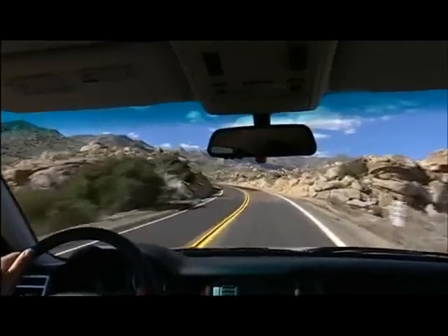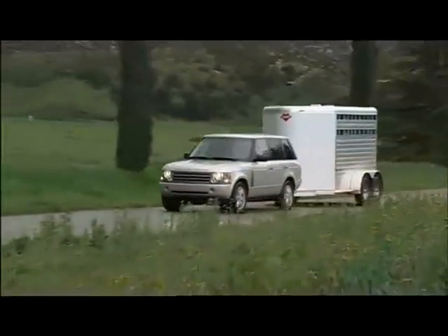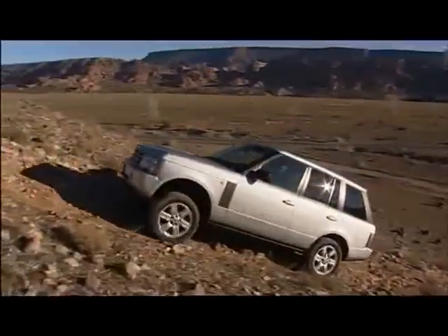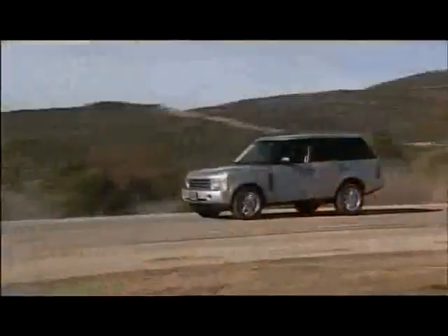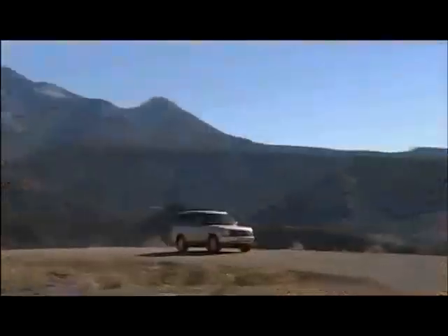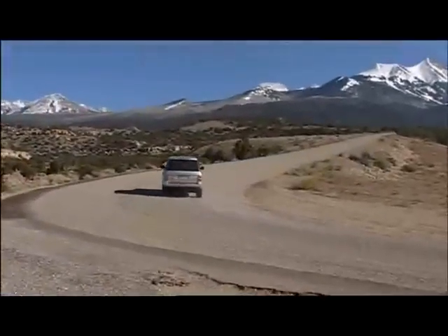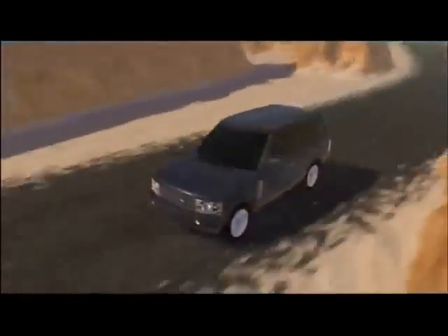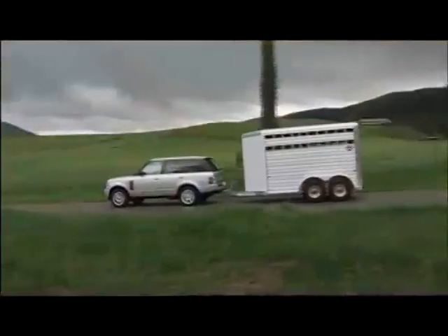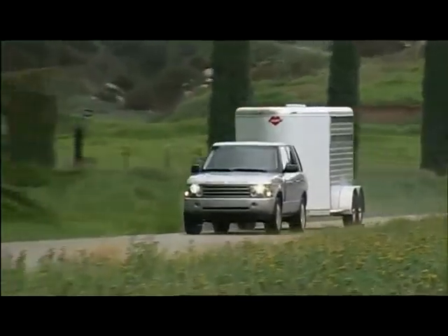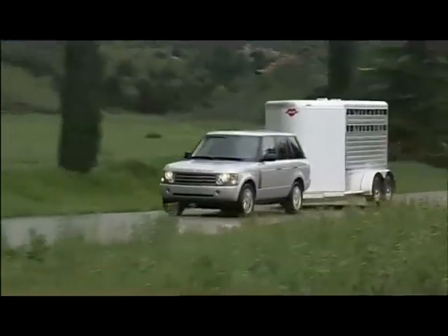A large share of Range Rover's capability can be attributed to its sophisticated braking system. ABS monitors wheel speed and varies brake pressure to prevent wheel lockup and allow the driver to brake safely. Cornering brake control regulates brake pressure through tight turns to reduce risk of over and understeer. CBC optimizes brake force distribution, helping to ensure vehicle stability when braking in a corner. When carrying a load or towing, electronic brake force distribution compensates for uneven weight distribution by balancing the braking between the front and rear axles.